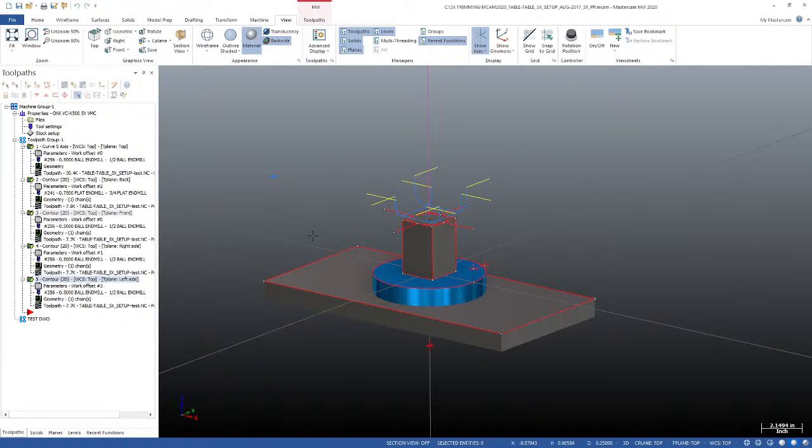So unless you pay the money to have somebody develop a post processor for you, where the output from the post is linked to machine simulation, and you have to pay for that option, the machine simulation that you see in Mastercam is really just using the centerline output of your toolpaths, and it has no idea whether your post is configured to match an individual machine.